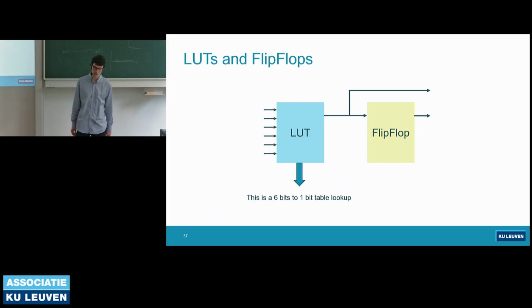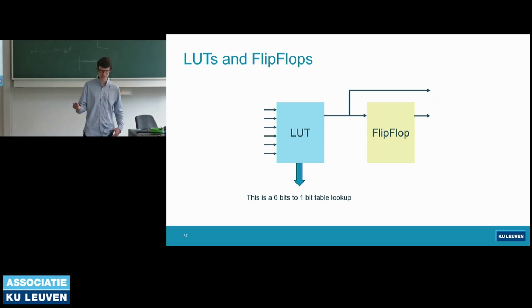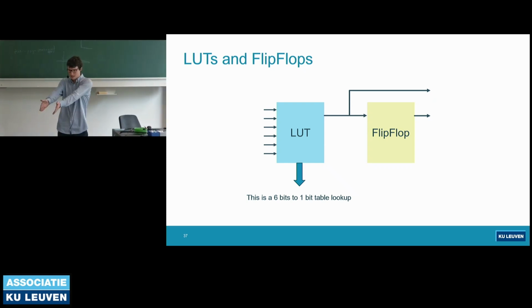But if you do K reduction, then you're going to get into the problem that you've only reduced 4 bits and you've already used one thing. On an FPGA, doing 7 additions instead of 1 multiplication is a perfectly reasonable thing to do. On a microprocessor, it's very rare that you get to do 7 additions instead of a multiplication, because the multiplication unit is right there.